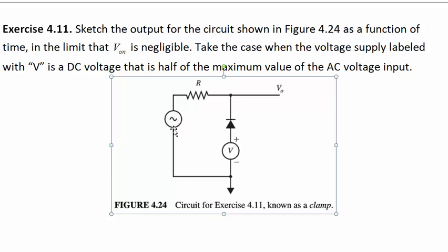Now, when this drops lower than this voltage, then the output voltage here would have been lower than this voltage, but now the diode will start conducting. So all the current that needs to will just go up through this diode and then across the resistor.